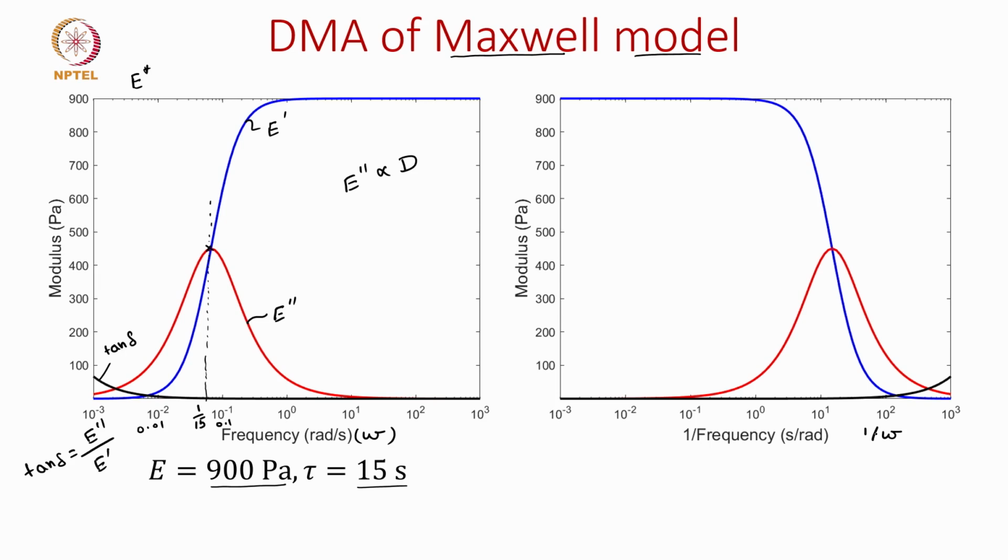Let us say this is a specimen and we are doing an axial test in a cyclic fashion. If I am saying that the frequency is small, it means the loading is happening very slowly. But in contrast, if I say the loading frequency is high, it means the strain rates or the stress rates it will see are higher, which means this also indicates time in this expression.